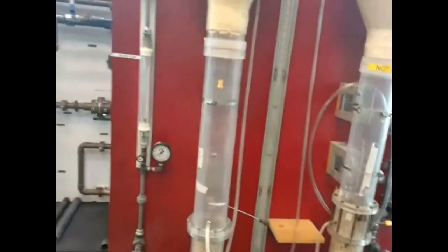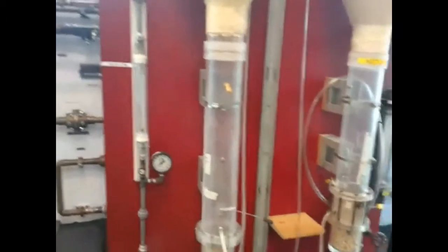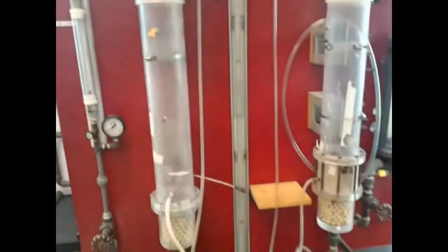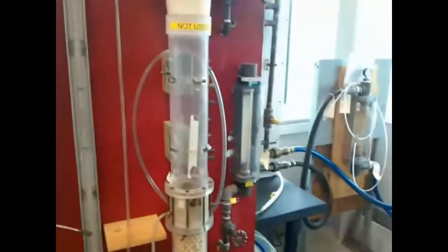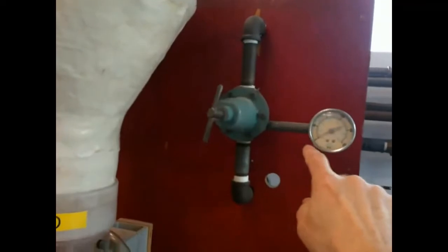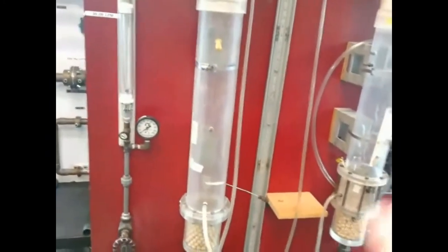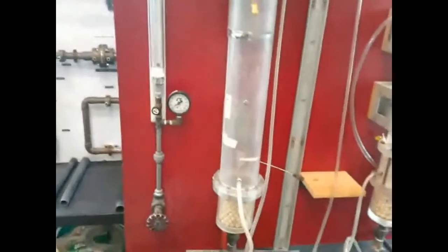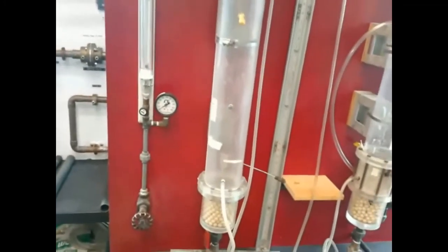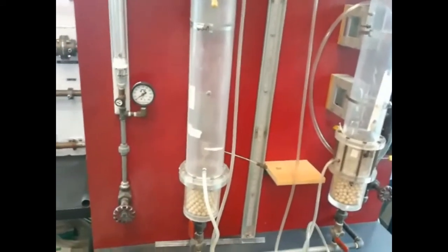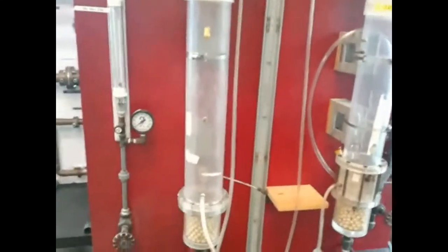But what we want to do is generate some motion in this column. That's why it's called a fluidized bed. We take air and bring it in through this point right here, our regulator, and the air comes down to the bottom and comes up the column. And again, this is all physics. If you have enough force of air, it will lift the column of particles and start moving them up and down. Then you get this really nice mixing of air and the solid particles and the reactants that you're trying to react. So this is, again, a very important process.